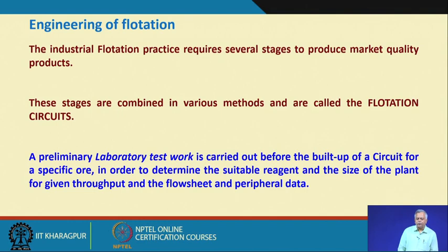So, for that, first what you have to determine is the degree of liberation, the liberation behavior of your iron ore. Then you may test the different reagents at different concentrations, and you should see where the response is the best. Of course, you have to keep in mind the economics of the process also.